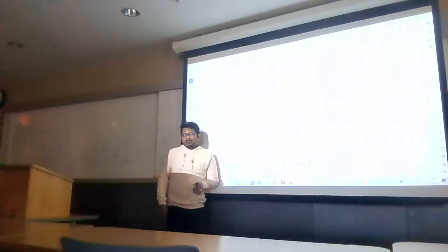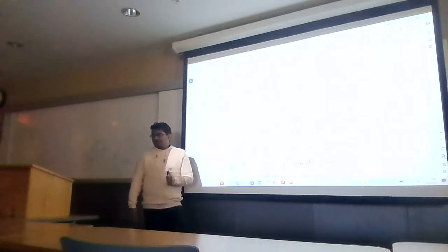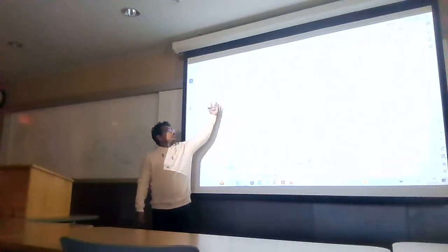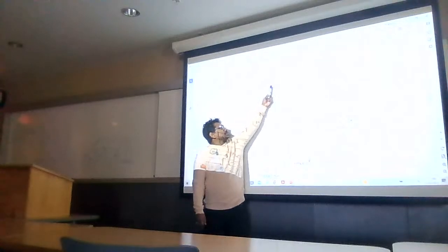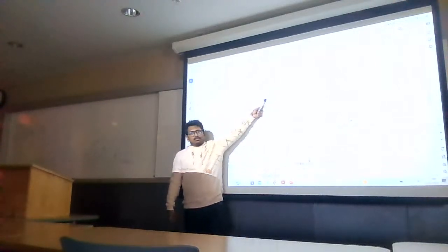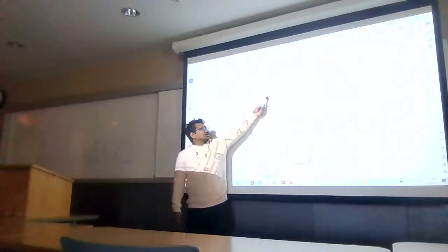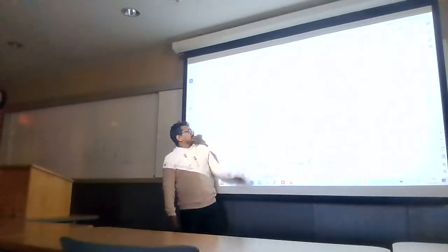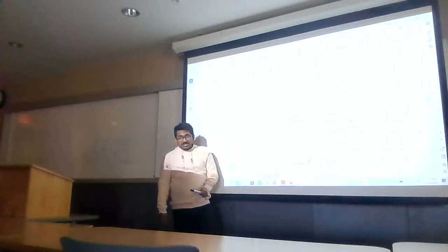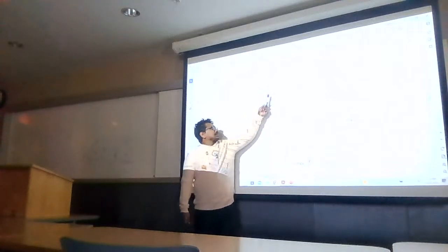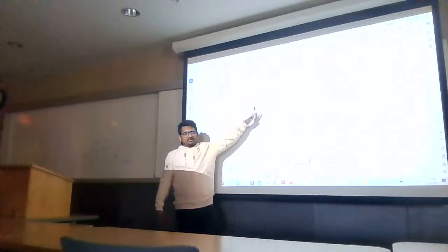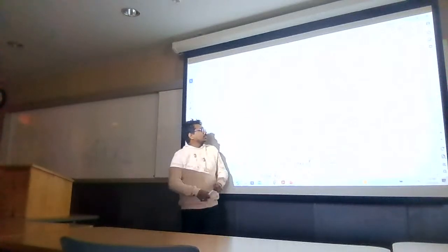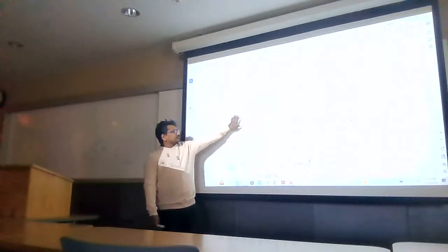If someone draws a circuit and asks how you can identify the name of the amplifier, typically, the input is connected to the gate, the output is connected to the drain, and the source terminal is open. There is nothing. So it is the common source. If I want to make it a common drain amplifier, then my output is connected here and the drain will be open. There is no other connection. So it is the common drain. Okay, whatever.